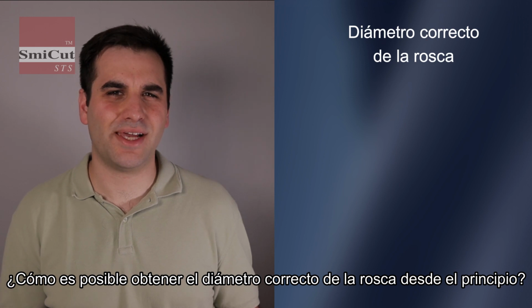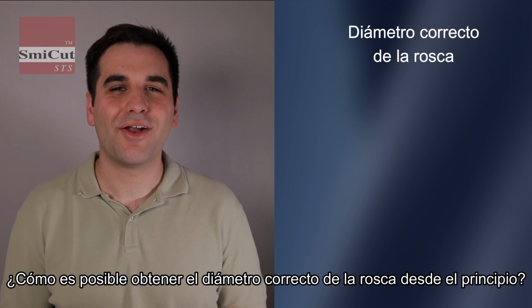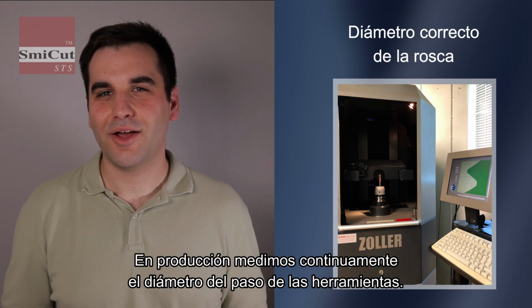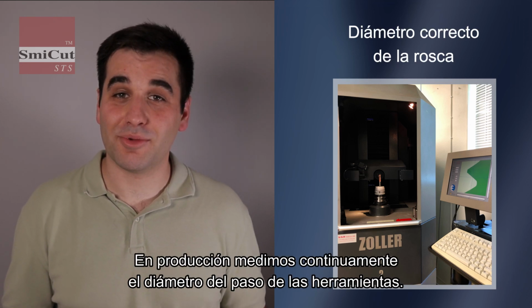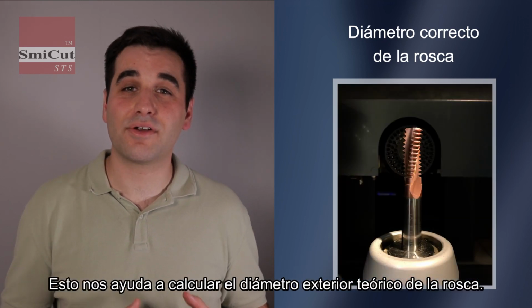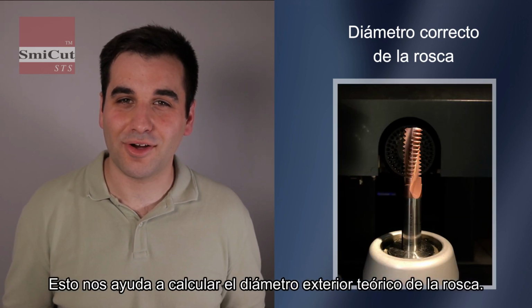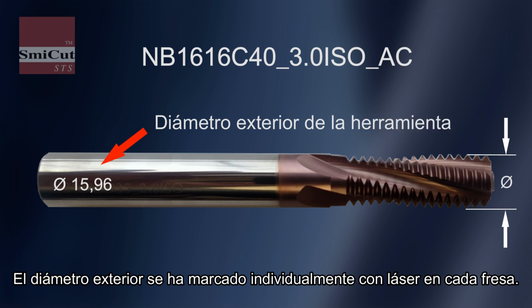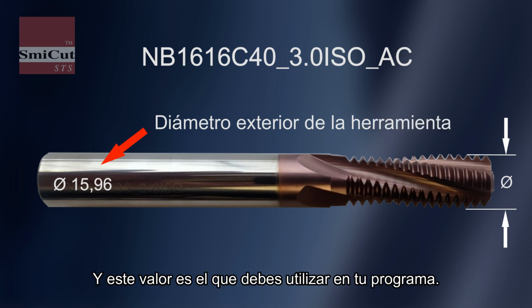How is it possible to get the correct thread diameter right from start? In production, we continually measure the pitch diameter of the tools. This helps us calculate the theoretical external diameter of the thread mill. The external diameter has been individually laser marked on each cutter, and this value is what you should use in your program.